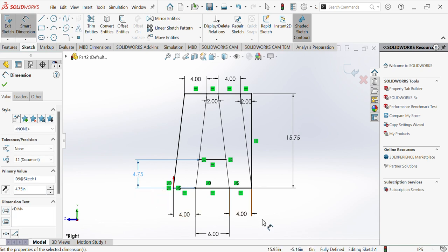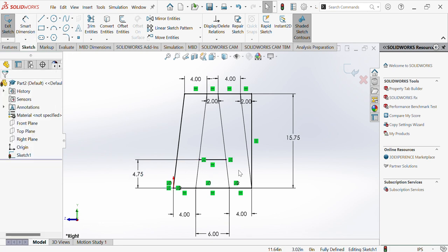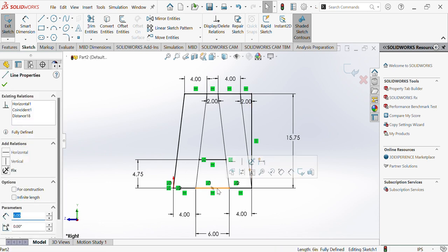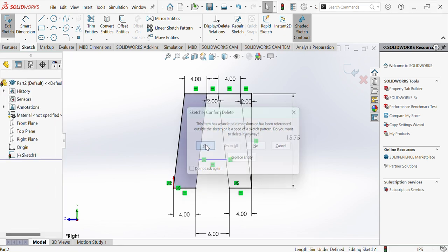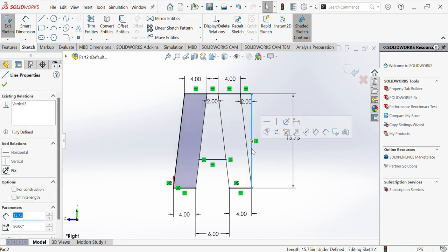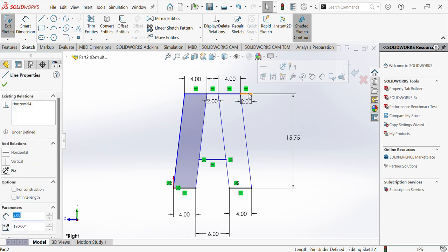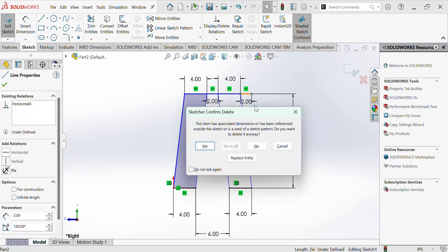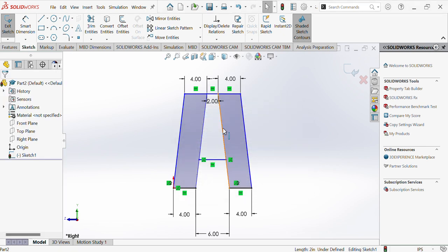Now that I have the correct slope and the correct height of this void that's going to be right here, now I can hit escape, and I'm going to get rid of some extra lines that we don't need. So this bottom line here, the far right line, top 2-inch part there, and then these overall long diagonal slopes.